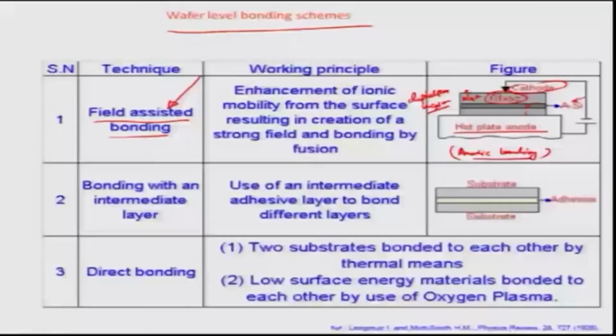At that point the silicon and the glass, heated because of the anode, are brought to a temperature where there is fusion bonding between the glass and silicon, but in the absence of the field. That becomes a permanent, irreversible bonding, and it results in thin cover slips getting permanently bonded to, let us say, silicon substrates which are highly structured or have printed electronics on the silicon.